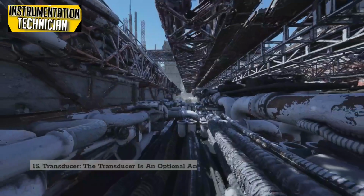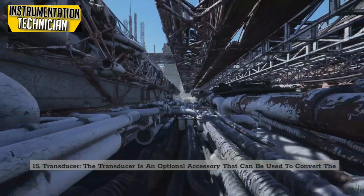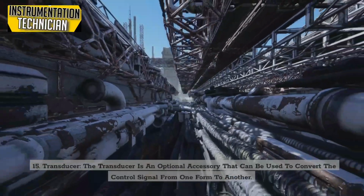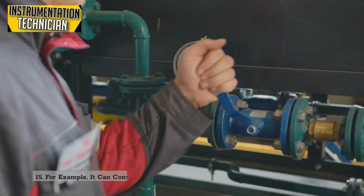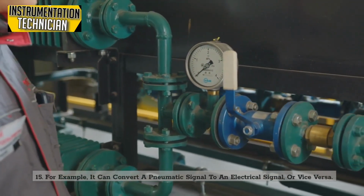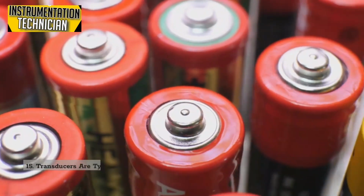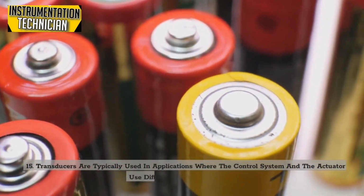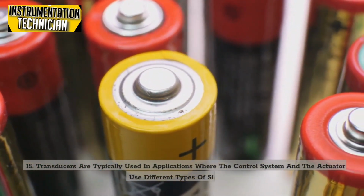Transducer. The transducer is an optional accessory that can be used to convert the control signal from one form to another. For example, it can convert a pneumatic signal to an electrical signal, or vice versa. Transducers are typically used in applications where the control system and the actuator use different types of signals.